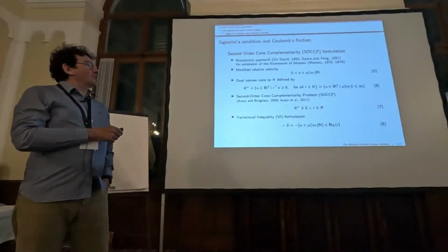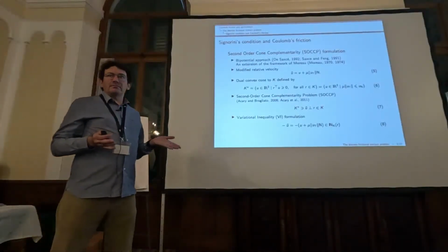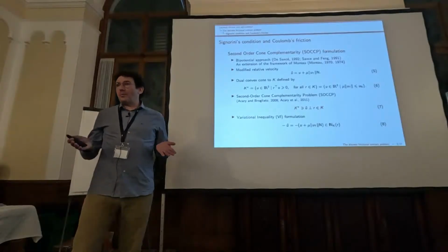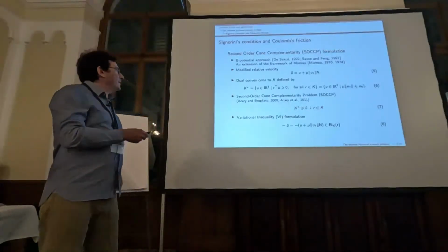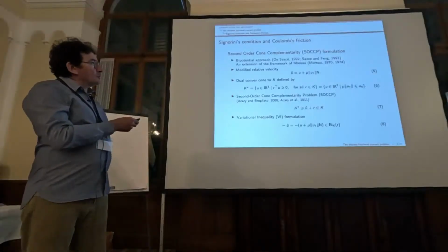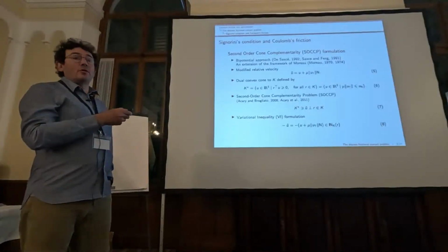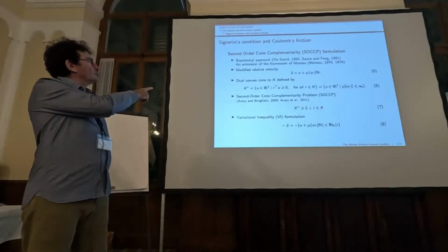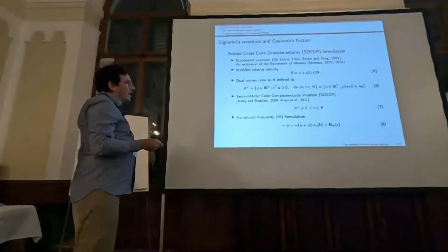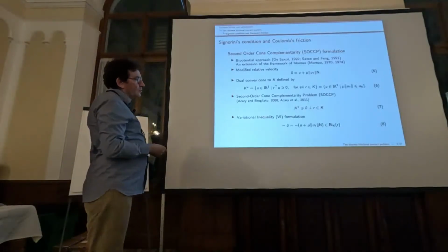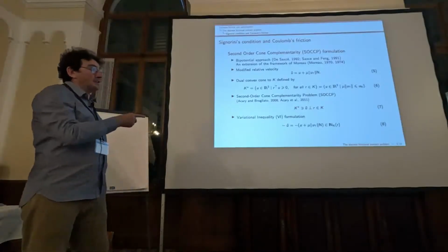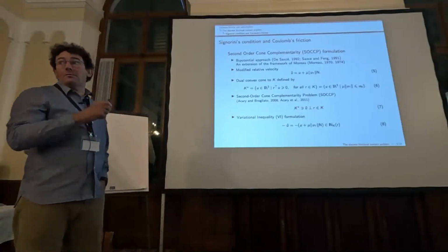We know that friction does not satisfy normality conditions, so the relative velocity is not normal to the cone when we slide. In that case, u tilde is modified such that it will be normal to the cone. If I introduce the dual convex cone to K, I'm able to get equation 7, a complementarity condition between u tilde and R, so u tilde and R are perpendicular.